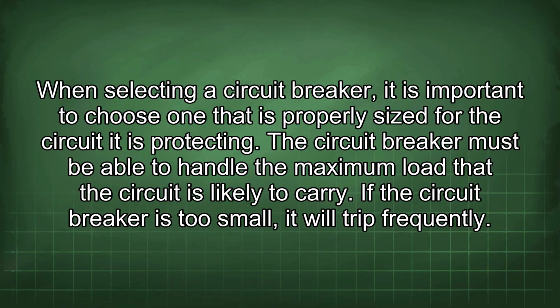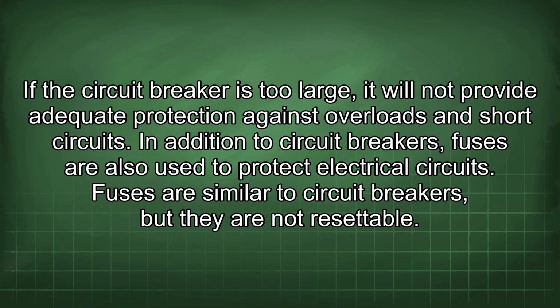When selecting a circuit breaker, it is important to choose one that is properly sized for the circuit it is protecting. The circuit breaker must be able to handle the maximum load that the circuit is likely to carry. If the circuit breaker is too small, it will trip frequently. If the circuit breaker is too large, it will not provide adequate protection against overloads and short circuits.